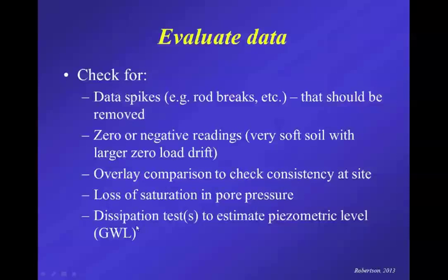Check for loss of saturation and pore pressure, and ideally carry out some dissipation tests, often at the end of the sounding, the deeper part of the sounding, so that you can get a reasonable estimation of the piezometric level. A lot of people do CPT with pore pressure measurements, but don't do dissipation tests. Even if it's just one, just do one at the end of the sounding or at some convenient location during the sounding. So if you're pushing through mixed soil conditions, through clays and sands, then sometimes stop within the sand layer and do a quick dissipation test just to verify the piezometric level and the piezometric conditions. So determine where the groundwater level is and determine if it's hydrostatic or not.